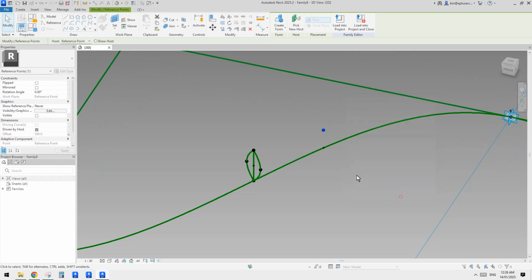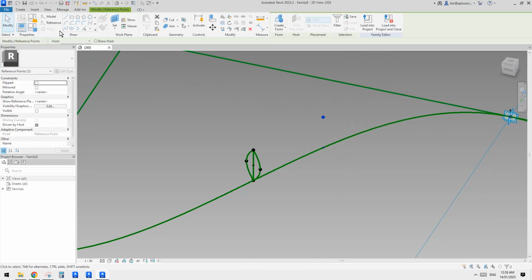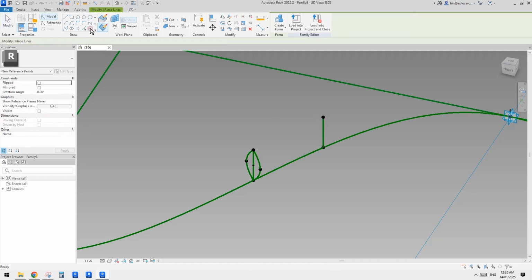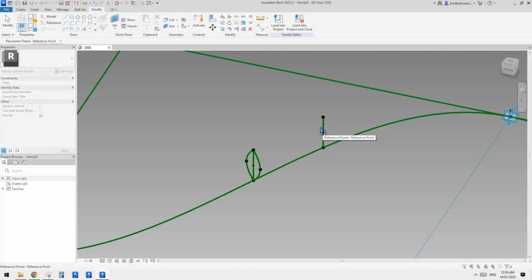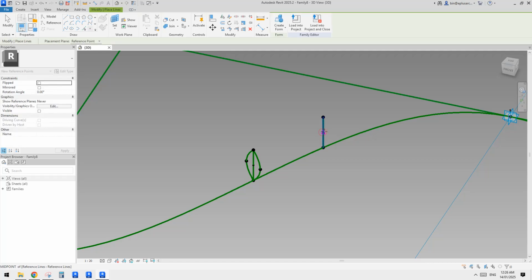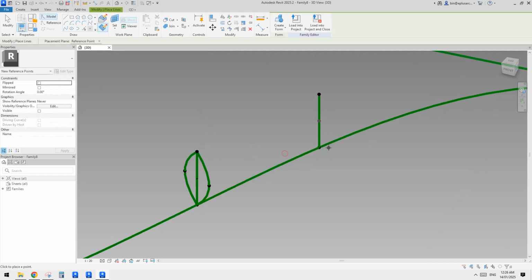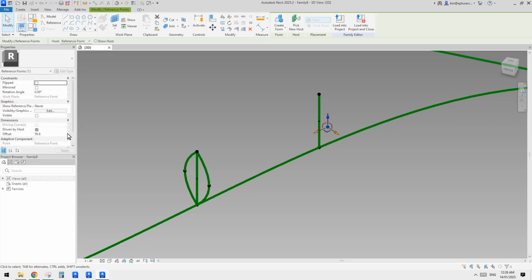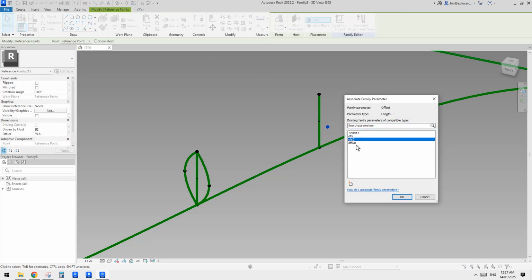Okay, and then connect these two, spline through points, make reference line, place a point, draw on face, place onto the reference line, and another point, draw on work plane, set work plane, tab, and pick that work plane, place a point, select this point and drag this, and this will be the offset 2.